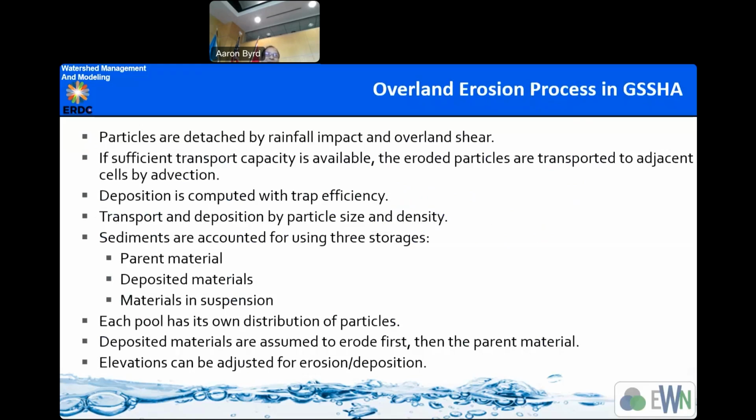There's a big flux coming there. But the sediment is well protected. See the terrace, so it doesn't flow away. So that takes account of the erodibility factor, the terrace kind of farming. It helps preserve the sediment, so the coefficient is lower for that. Those kinds of things. It's very practical, cause and effect relationships.